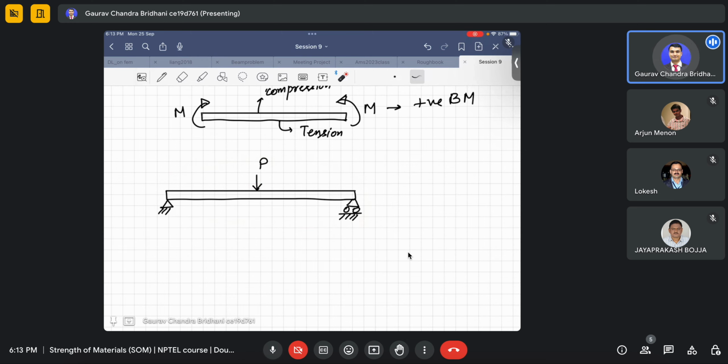You will see some variation like this, and that is very important, because that's how you have learned how at 45 degrees there is a shear, and that shear is causing tension on one side and compression on the other side. That is very interesting, because in literature and textbooks they hardly derive the equations for these curves. But by looking at the video or the picture you can see how those curves are coming.